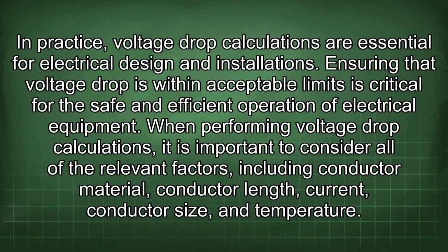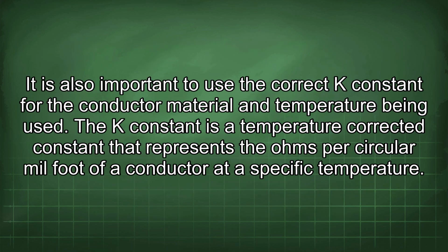In practice, voltage drop calculations are essential for electrical design and installations. Ensuring that voltage drop is within acceptable limits is critical for the safe and efficient operation of electrical equipment. When performing voltage drop calculations, it is important to consider all of the relevant factors, including conductor material, conductor length, current, conductor size, and temperature. It is also important to use the correct K constant for the conductor material and temperature being used.